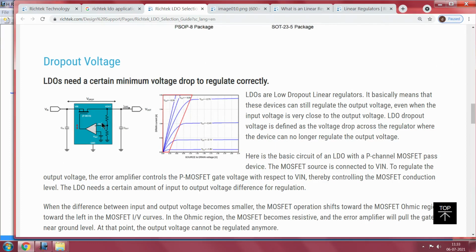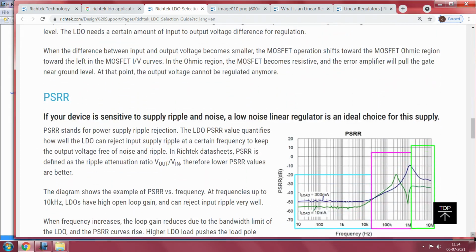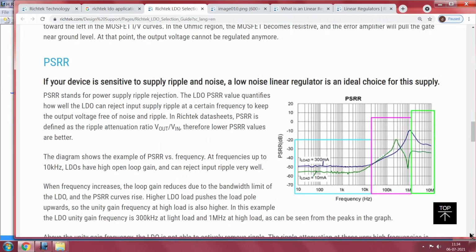But it still gives you very good ability as long as you are able to maintain the required drop, the system is under very good regulation. So that discussion is mentioned in this paper as well, and the process simply gets reversed in the case of the N channel MOSFET. I would want you to explore how that happens and why a charge pump would be required there. What is next is, we discussed enough about the LDO and its functioning, but what we did not